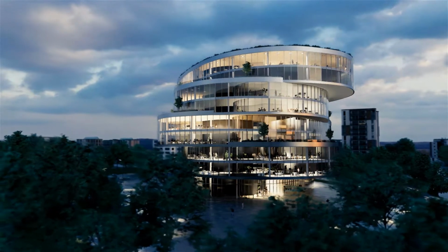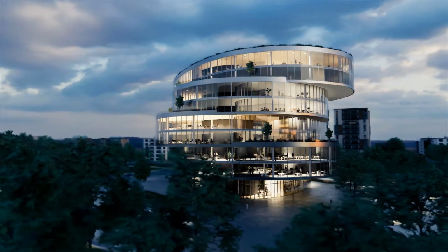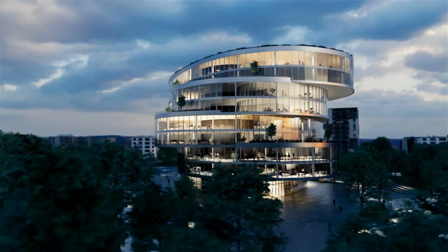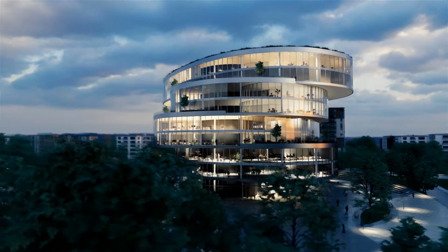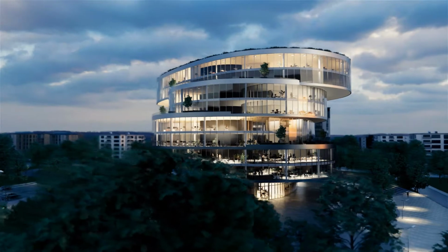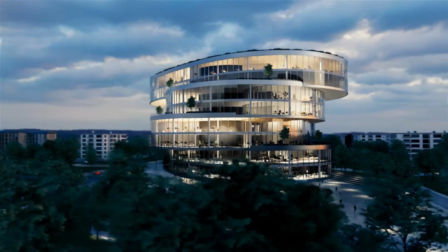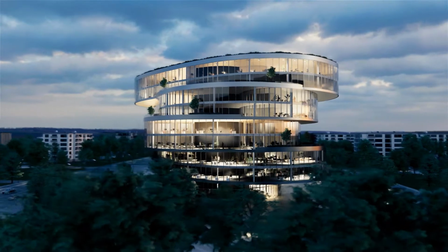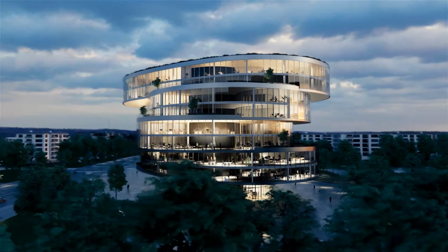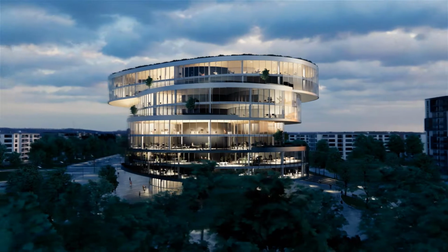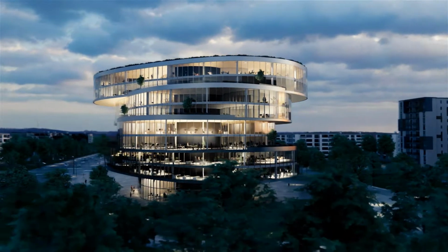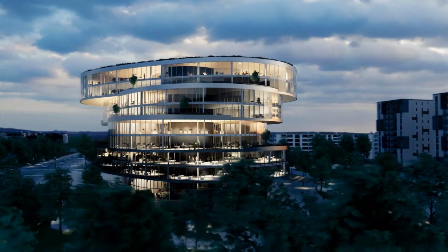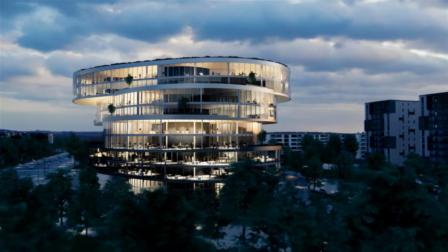Animations. So to create this animation in Enscape, we simply define the camera path. We set keyframes to define where we want the camera to look, and then we can adjust the time between the frames to speed up or slow down the animation transitions between the frames. Enscape makes it very easy to create stunning animations like these. It's a very straightforward process. Also new in 2.9 are atmospheric effects.